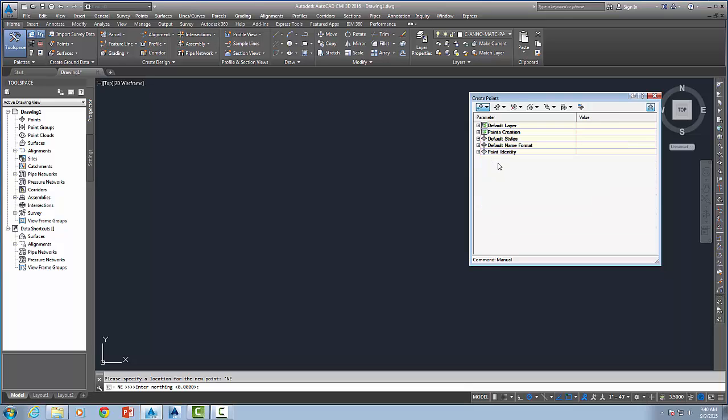The other thing I want to do is go down here. Let's look at styles a minute. I want to show you the current style that's going to drive these points is set to what's called a basic style. That's how it's going to look. And in the label style here, it says point number, elevation, description, which we'll see won't show up, but we'll have to make that come on. So those are your styles. Notice they're grayed out, so you can't do anything with them.